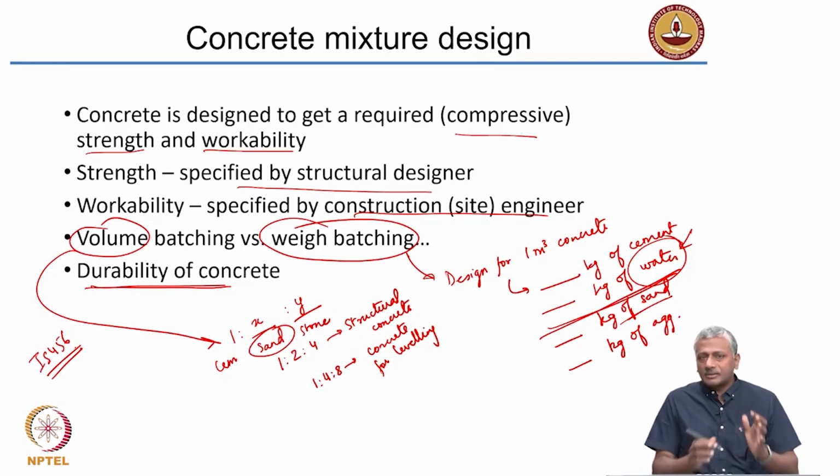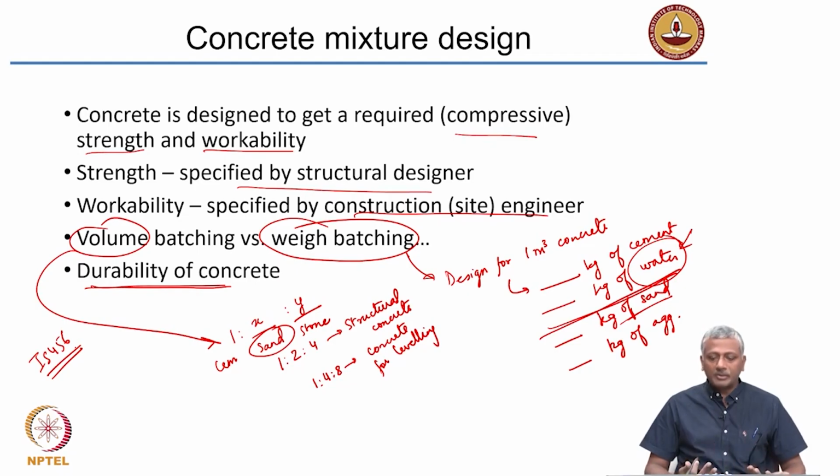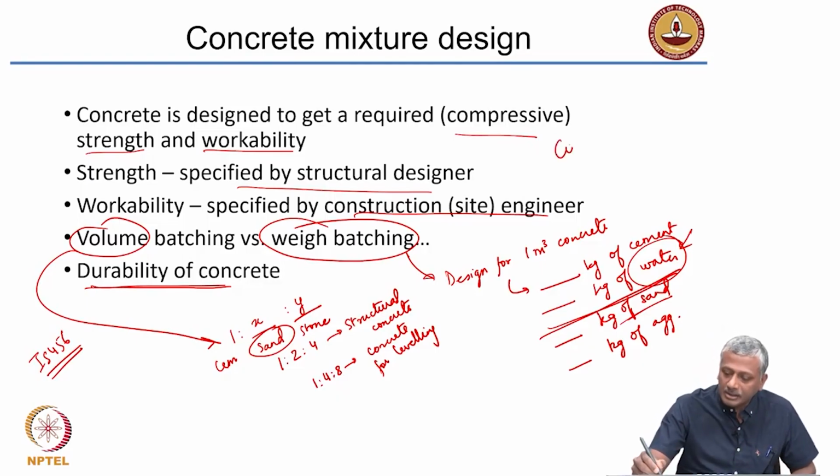In most cases, strength is not really a consideration because we usually over design the structure with respect to strength. But with respect to durability, if we don't have a clear understanding of the environment and what can happen in that environment, we could be in for a lot of problems with respect to the concrete structure. So, today increasingly the focus is shifted to durability, and because of this there is one more additional person that needs to come in for large projects, and that is a concrete technologist.